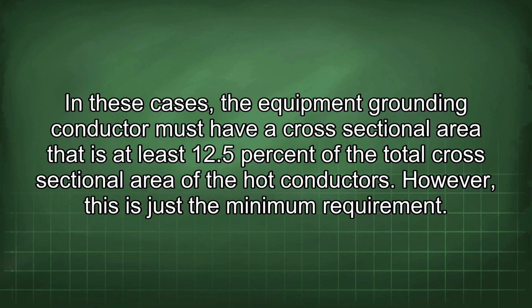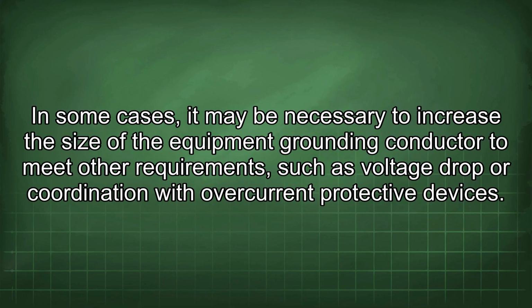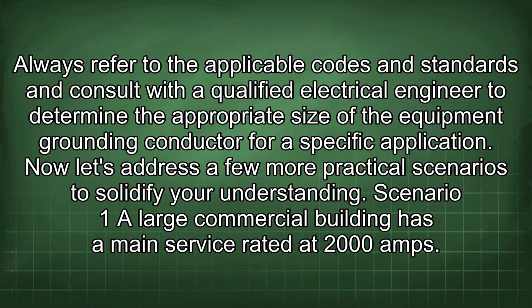However, this is just the minimum requirement. In some cases, it may be necessary to increase the size of the equipment grounding conductor to meet other requirements such as voltage drop or coordination with overcurrent protective devices. Always refer to the applicable codes and standards and consult with a qualified electrical engineer to determine the appropriate size of the equipment grounding conductor for a specific application.